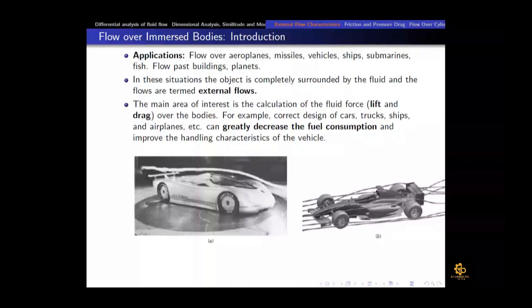And for the ground vehicle, drag force is the major thing, which is the design criteria, because we want to limit the fuel consumption. Like in cars, basically they are quite thin. The frontal area is very low. It means that the bodies are streamlined bodies. So it means that we have less drag force on that. But if it is a bus or a truck, then the frontal area is more, and for those cases the consumption of fuel is quite high as compared to some cars, right? Like Formula car racing, they are very thin, kind of streamlined. It means the frontal area, or the area on which the flow is going to strike that surface, is very low. So that drag force is very low.